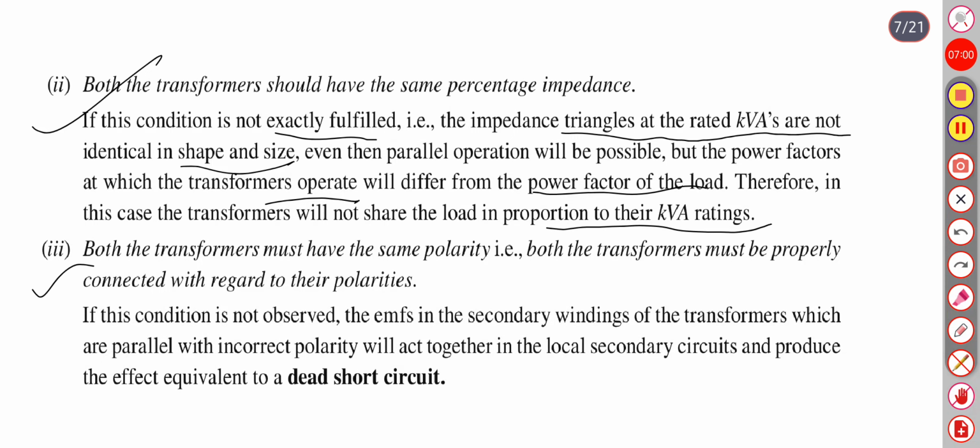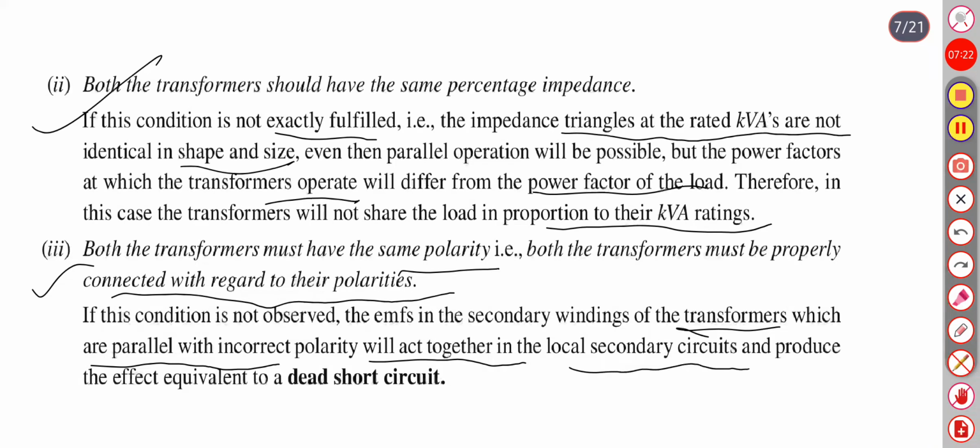Next, both transformers must have the same polarity. Both transformers must be properly connected with regard to their polarities. If this condition is not observed, the EMFs in the secondary windings of the transformers which are in parallel with incorrect polarity will act together in the local secondary circuit and produce the effect equivalent to a dead short circuit.